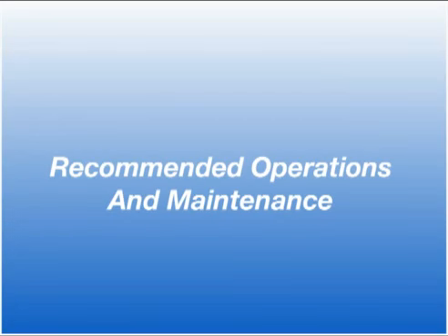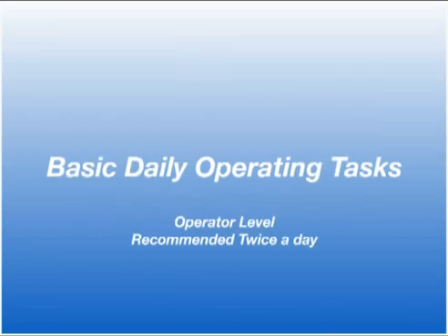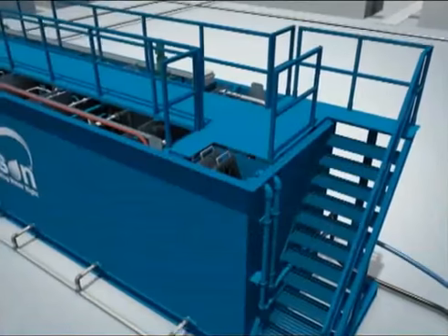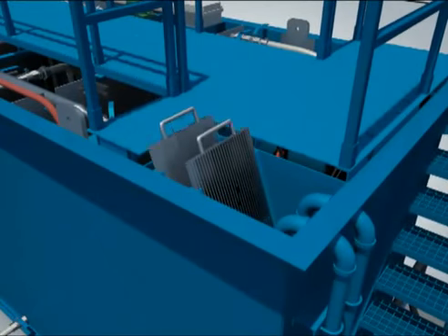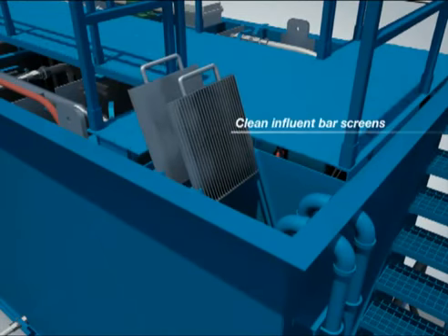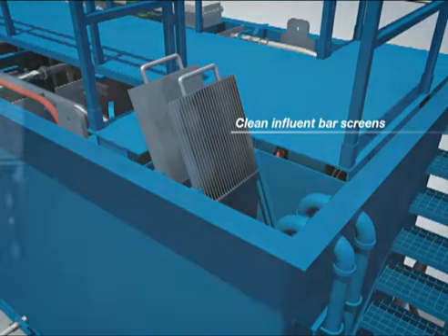Recommended operations and maintenance. Basic daily operating tasks, operator level. Recommended twice a day. Clean influent bar screens with a broom into a trash can as often as required.